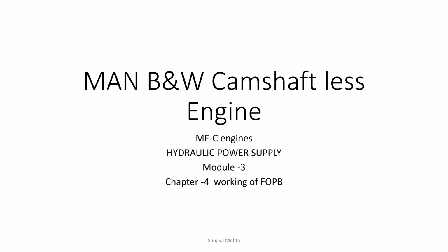Hydraulic power supply, because the actuation of the FOPB, the exhaust valve, and cylinder lubrication is all carried out by hydraulic pressure, not by mechanical force as in the conventional engine, because there is no cam, no camshaft, no drive shaft, nothing. So naturally, hydraulic pressure is used. All right.